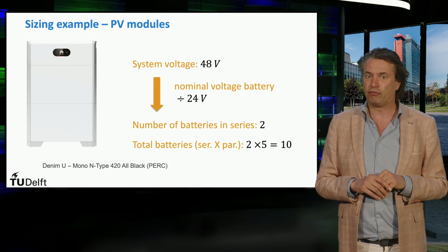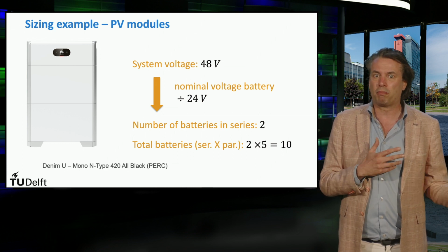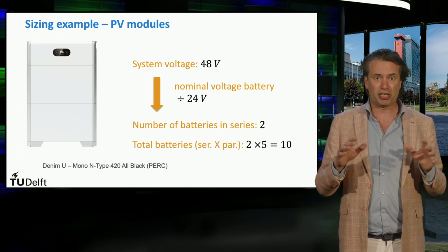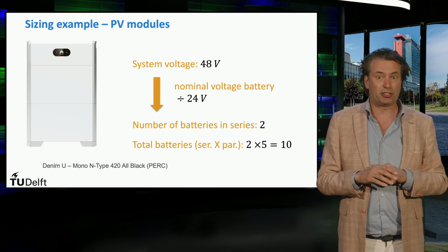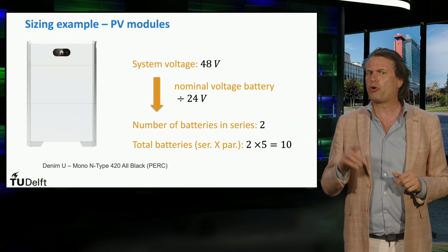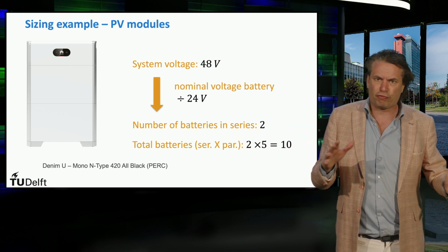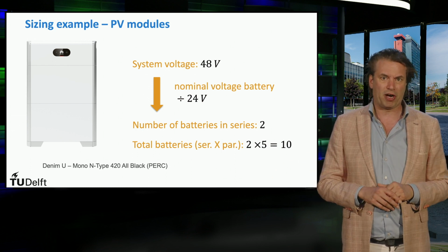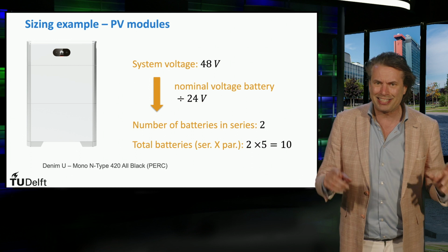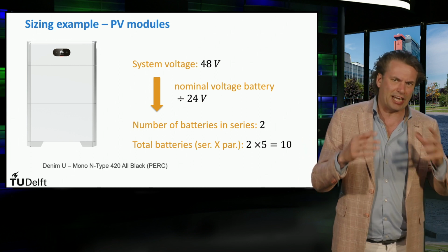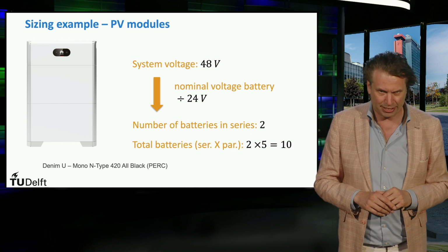For places with severe disparity between the summer and winter irradiances, the number of autonomous days would increase for winter and the system cost would consequently rise as well. Also, the component margins considered for the various parameters could differ from place to place based on the system requirements. Nonetheless, this method is good enough to get a basic estimate of the standalone PV system sizing.